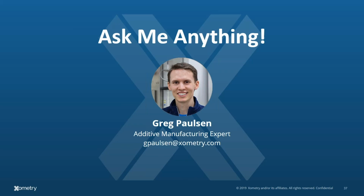Great. So we have another question from Andre. What material would you recommend for extremely low temperatures? All right. So I used to work in ruggedized military devices, and the extremely low temperature is usually a loaded question because I've done SLS nylon housings that have gone to that -40 to 140 requirement, but usually that requirement has a little caveat where it's for more like a cargo transportation.